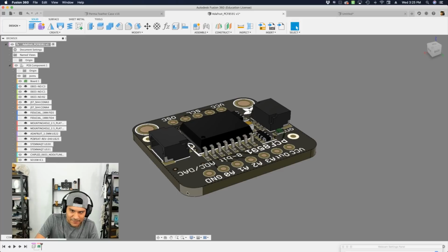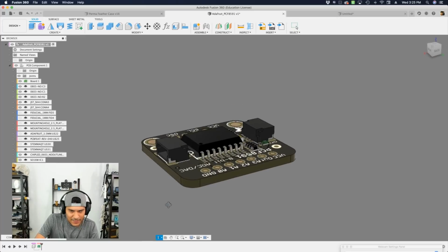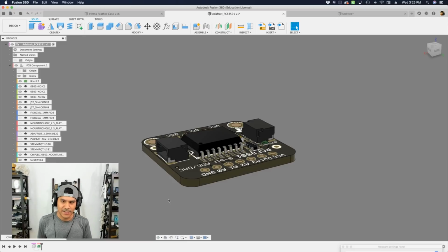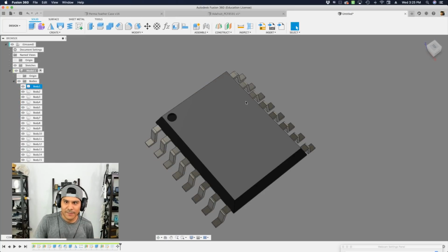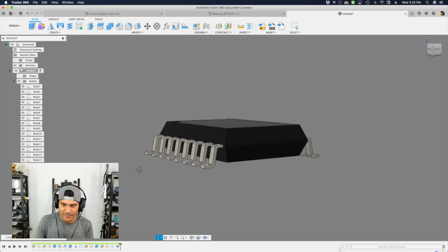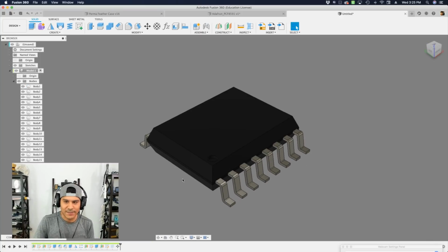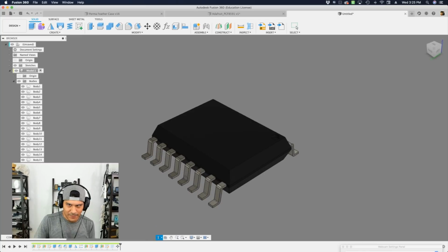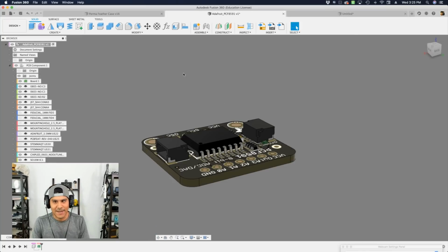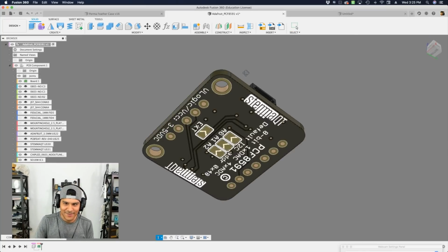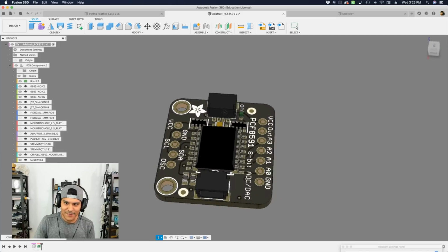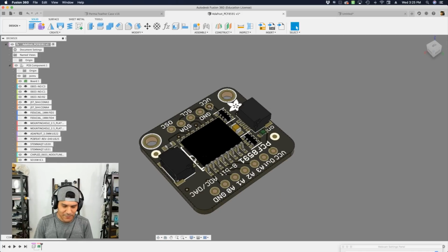So that's how the workflow is to manually set these components to your freshly imported PCB from Eagle. But hey, I think folks that use KiCad, they can use the package editor to create these models, export them out as a step, and then bring them into their own tools. So that's a really fun thing. There is some more work that's going to be done, like more packages are coming. That's really cool. I'm kind of missing the LGA packagings, but hey, you got some great ones to start off with. But that's kind of the workflow.